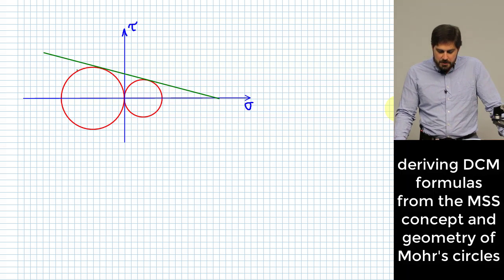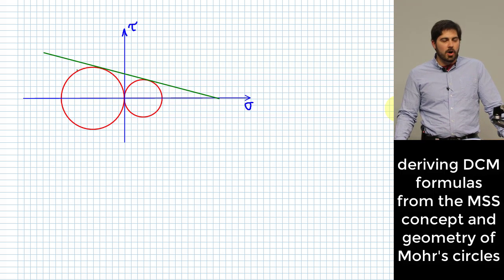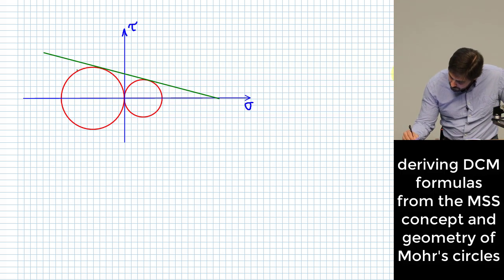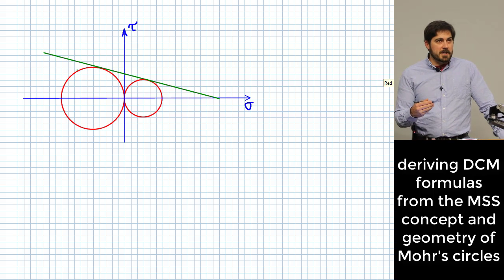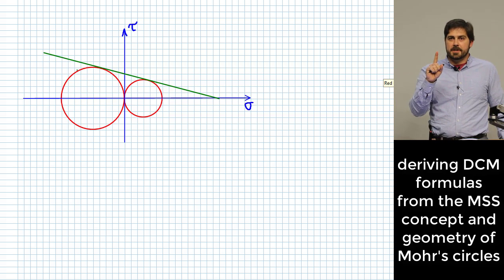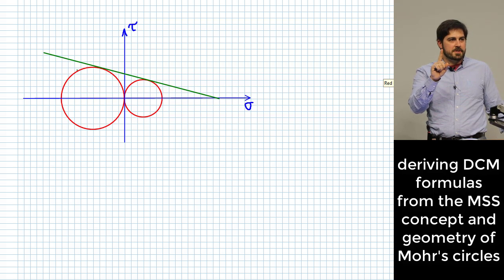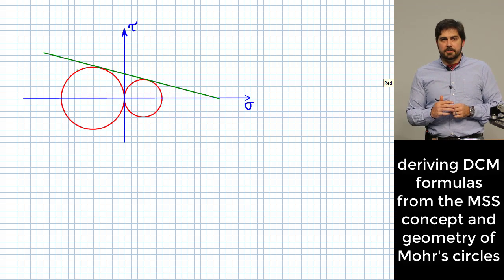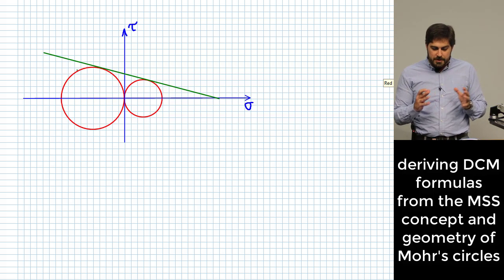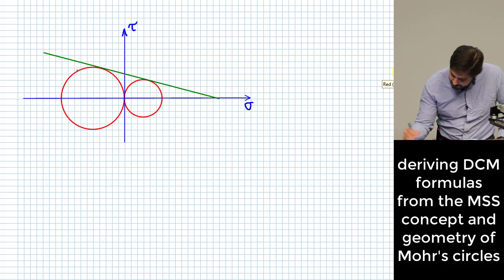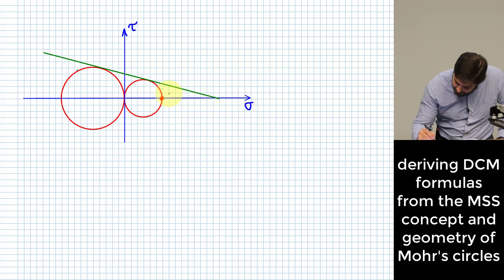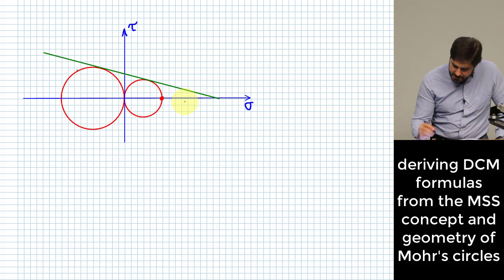And that's what these two circles represent on this chart right now. Imagine here, for a tensile specimen, you have one component of stress applied. It is one of your principal stresses, and the other two principal stresses are zero, right? And you load it to the point where it begins to yield. You load it right up to the point of yield, and that is this point right here. So we'll call that value S sub y.